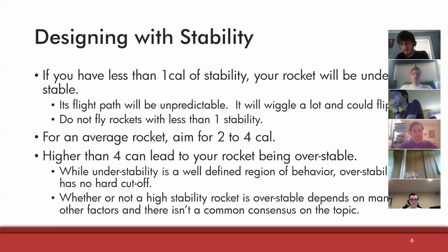In any case, as you're actually designing a rocket, you'll typically have to work with where the CG and CP are and change fin shapes, mass distributions, etc., to try and get them to be a good distance away.